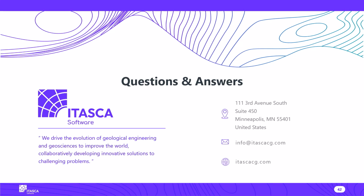But again, Dave, I think it's important that for this sort of detail-oriented analysis, it is still better to get the cave geometry from, let's say, a caving model, and then put it in this detailed model, because these are very slow models. You have a zone size of 40 centimeters. So we try to decouple, because in the caving analysis, you use larger zones. Those are quicker. So we complement both. Great, thank you. That's definitely a very finely zoned model.